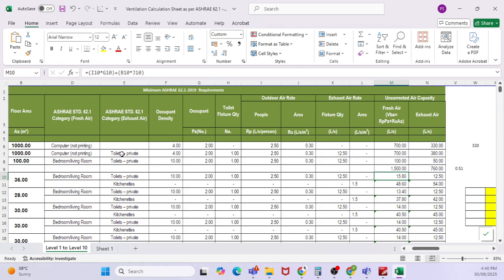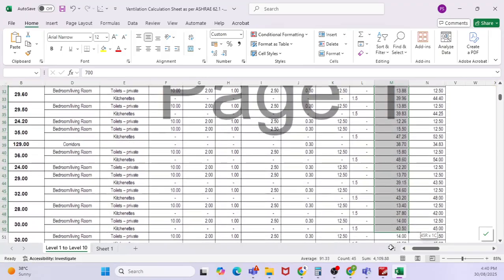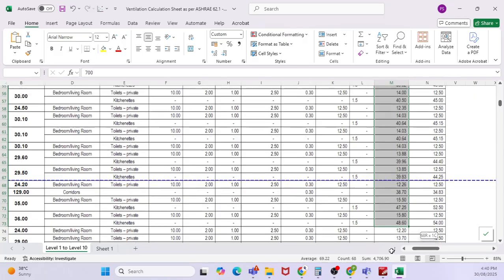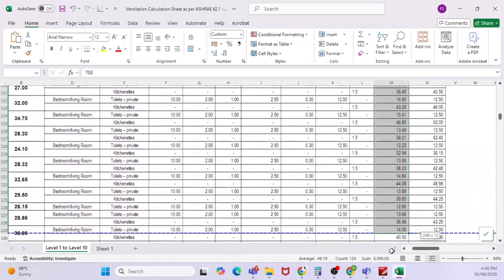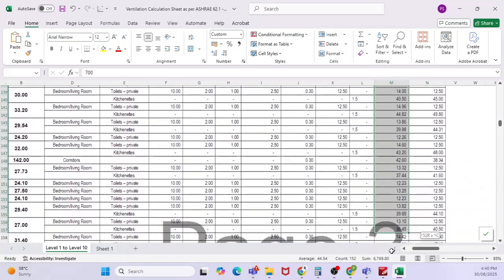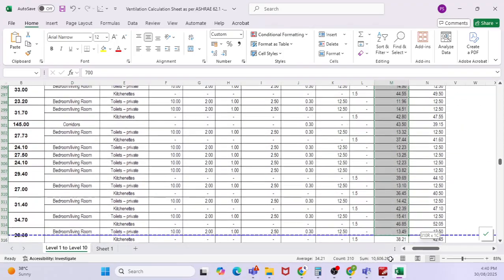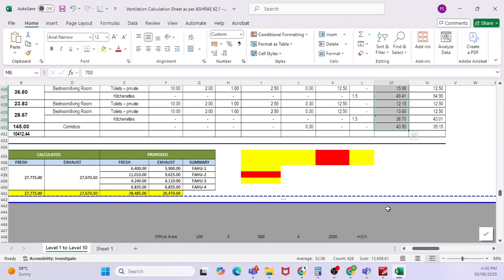So when you calculate the fresh air requirement for each and every space, you will add up each and every space, right? You have, say for example, 100 spaces, because a fresh air handling unit is a huge equipment. You can provide it for maybe multiple rooms. So when you add all the fresh air, based on the same equation applied for each and every space, you will come up with the total fresh air requirement.